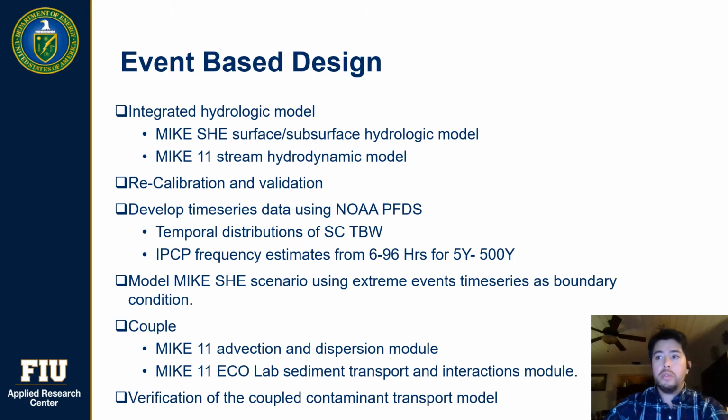The horizontal conductivity band was assigned using the auto calibration process, and this was then executed using the model server, in which about 1,200 runs were combined in order to obtain the most influential parameters for the model. So in order to simulate the extreme events, we chose a 1 to 500 year range and performed an analysis in which different spreadsheets with time series were developed.